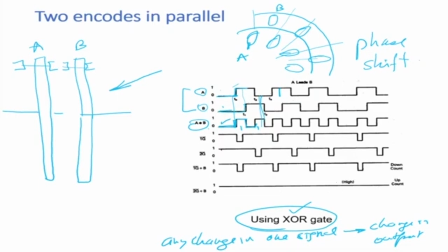So in an industrial robot, the encoders have like 1000 counts per turn, or 500 counts. CPT means counts per turn. That means how many holes there are. So 1000 CPT is pretty high, so it is 360 divided by 1000.